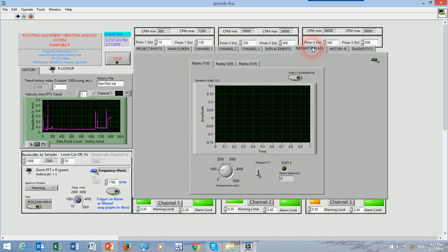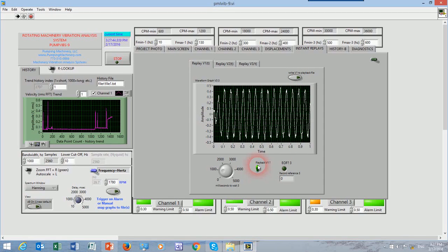Some of you might be interested in more detailed analysis of spectral signals, so we can add velocities of other channels, accelerations, and some might be interested in overall trend, a more expanded view. We can do that too. But in this case, I'll push this button, which is write V1, velocity 1, to the playback file. It's writing into the file as we speak, while the data acquisition continues taking the data. If I stop it now and I want to replay it, I just hit playback.